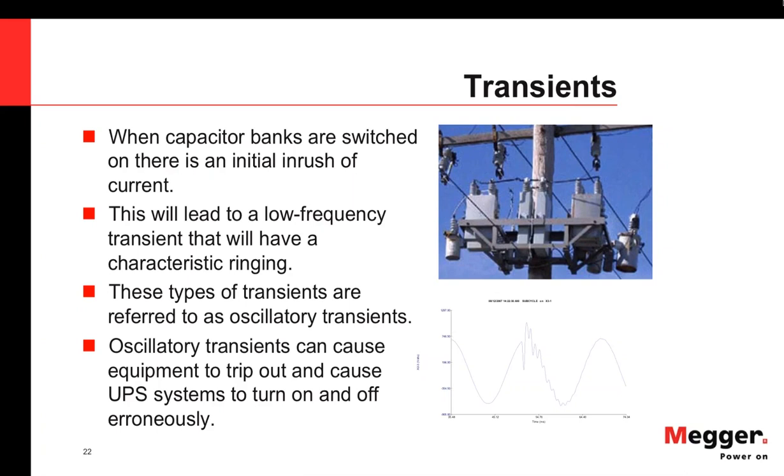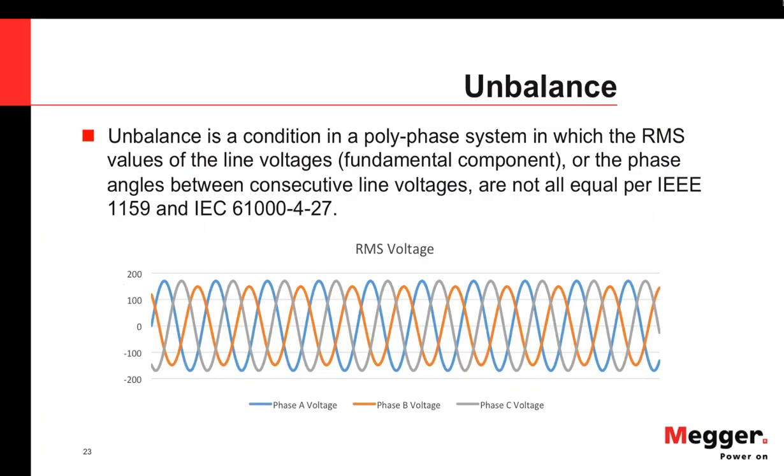As the loads are turned on, cap banks are switched in to compensate for the inductance of the loads, and you get these ringing events that occur. UPSs can switch on and off quite frequently. And one of the things to do to correct this is lower the sensitivity of the UPS so that you don't have it constantly switching on and off, because they do have a limited lifespan based on how often they turn on and off.